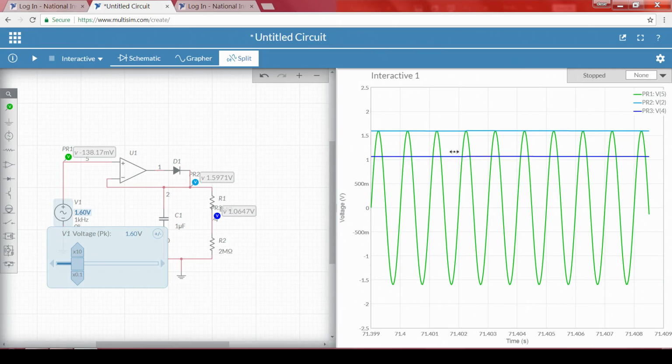So, in order to do that, what do we have to use? We have to go with a comparator. A simple comparator is enough. We do not have to go with any Schmitt triggers, because we are not setting two thresholds here, we are using only a single threshold. If the input value is greater than this value, only that signal has to be passed, detected, and counted.